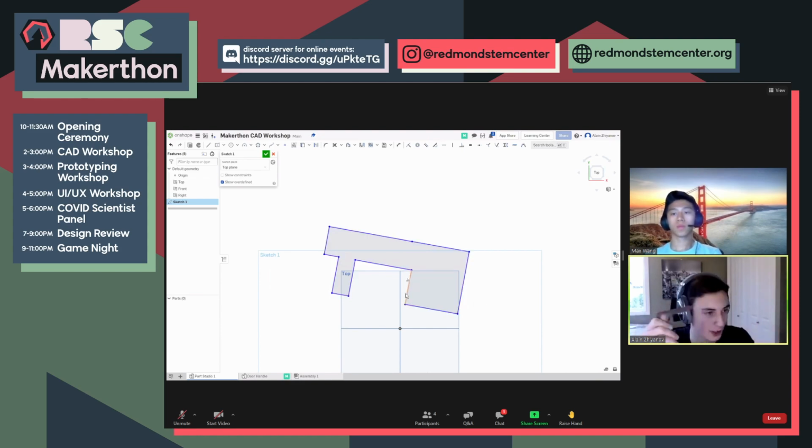And if I'm going to go ahead and 3D print this, well, these could be 3 feet by 3 feet, and that would be way too big. So let's go through the dimension constraint, which is arguably the most important constraint, and it's up here. What this means is you select a body or maybe a distance between two bodies, and you can just set a distance for that. So for example, let's say I want to set a distance between these 2 points. I want to select a distance for this line here. Right now it's 1.46 inches.